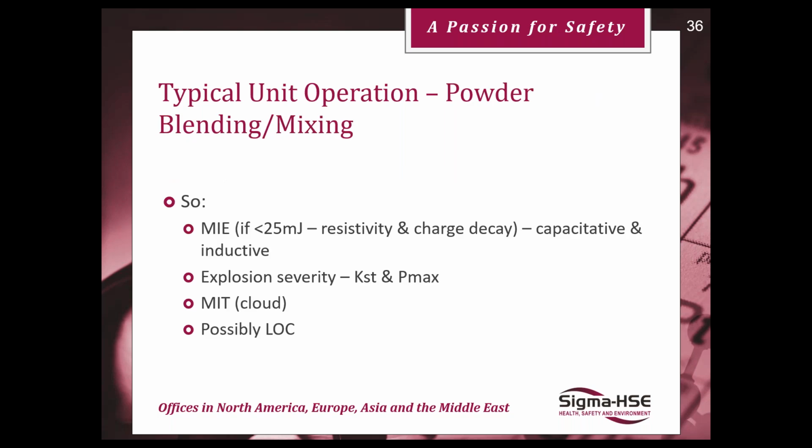Similarly, blenders and mixing: again, MIE is important, because the resistivity of your powder or of the liquid, and how quickly it can decay its charge, will have an impact on the likelihood of having electrostatic ignition sources. So MIE is necessary to understand there. That sets the limits on our system. Explosion severity is important, so we'll need to understand the KST and the Pmax.